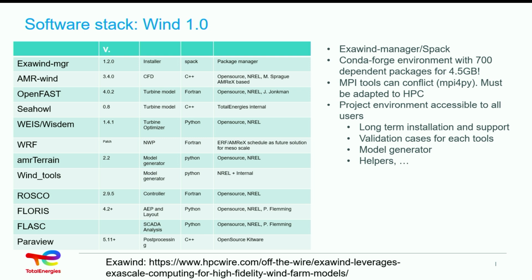So the core tool here is a computational fluid dynamics software called AMR-Wind, based on the AMReX framework, kind of similar to Kokkos for those who know. And this is block-structured CFD software with capabilities to model the turbine with an actuator disk, a simple model, or to couple with other software like the OpenFAST multiphysics software.